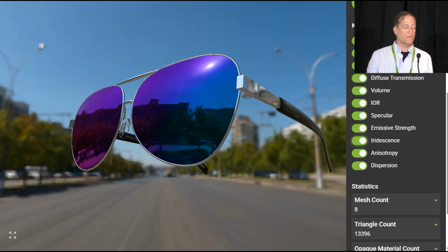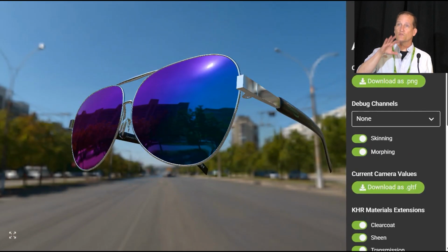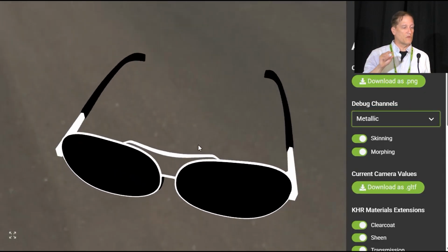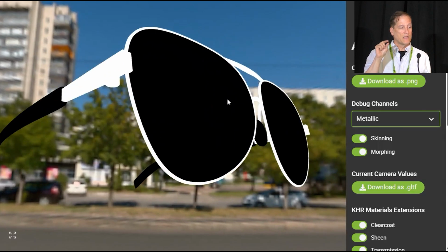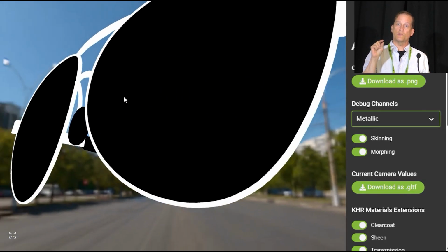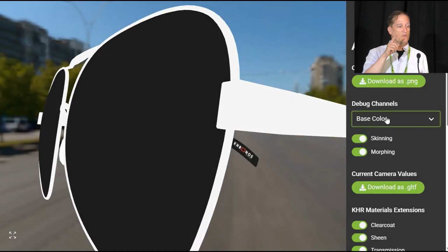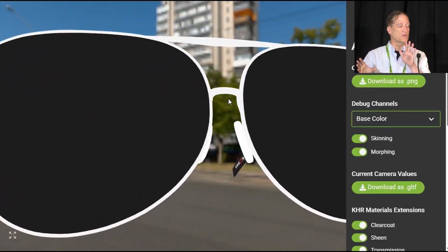This also uses something called face-weighted normal map, or face-weighted shading for the normals for the surface. So all those metallic surfaces have very limited geometry, and they don't use normal maps, which can add to the size of the file. So they actually use normals that are aligned with the largest faces of the surfaces.